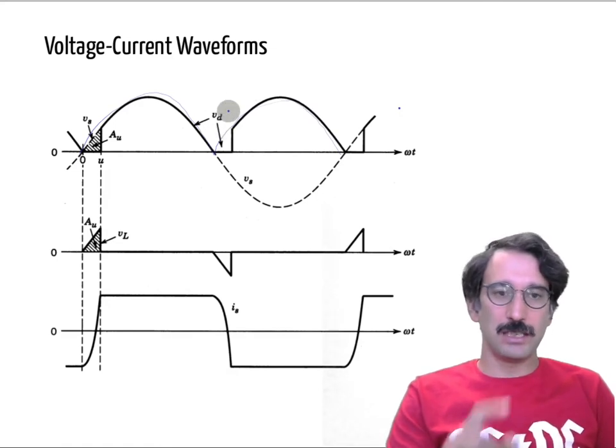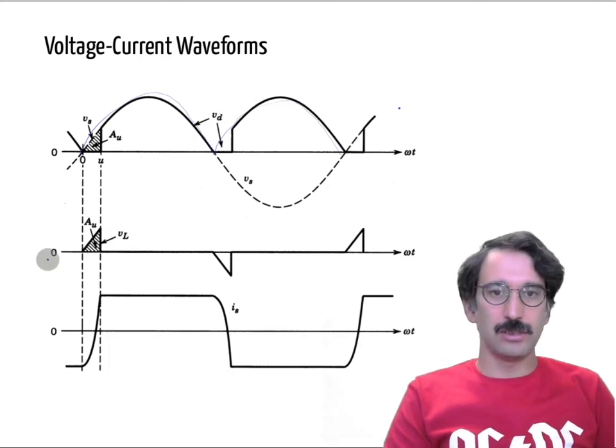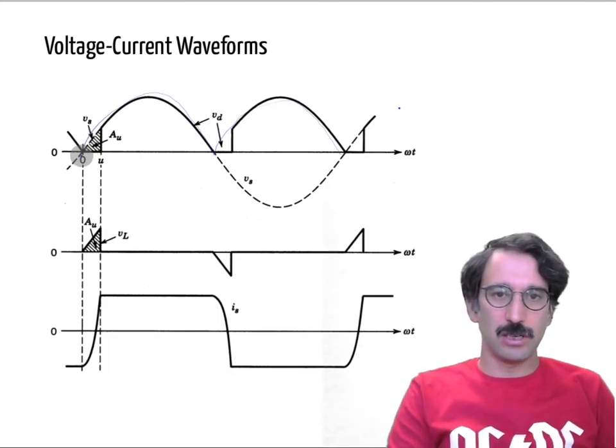But now commutation happens twice, both from positive to negative and negative to positive regions. So I will have some 0 volts for some time. Then my output voltage will increase sharply. During that period, I cannot go to negative because of the diodes, and I will have another jump here.